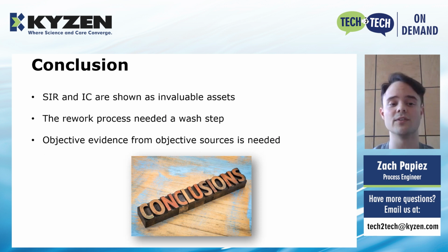The combination of surface insulation resistance testing and ion chromatography emerged as invaluable tools for evaluating the potential risks associated with various process conditions. In particular, the processes that involved the rework procedures were found to be in need of an additional crucial step, namely a thorough washing process.